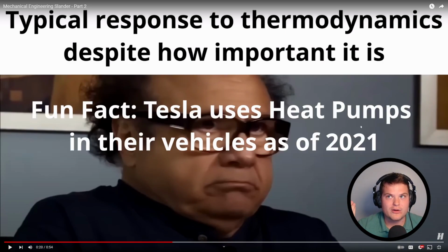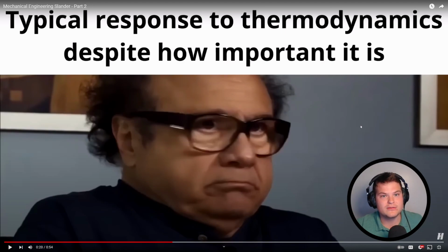You're creating a cold radiator outside to absorb heat. Say it's 70 degrees out, which I don't know why you'd have your heat on then, but say it's 60 degrees out and your radiator outside is 30. It's going to absorb heat and pipe it inside. And then your furnace is going to turn the blower on and blow it over your A coil, and it's going to heat the house. So that was really helpful in knowing that.